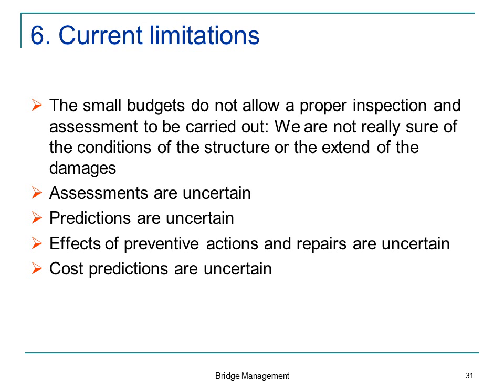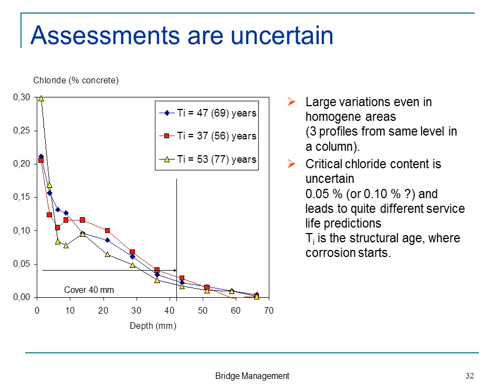And let me illustrate it. We do, for instance, often drill out a core from a concrete and we slice it up and we measure how much chloride, how much of the salt has penetrated into it. And then we know that if there's a concentration of 0.05%, then we probably have corrosion. Some say, no, it's better with 0.1%.